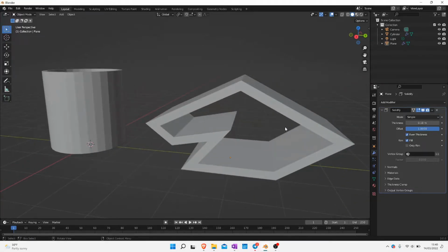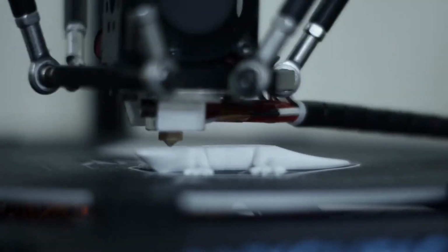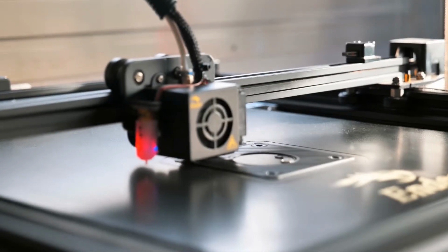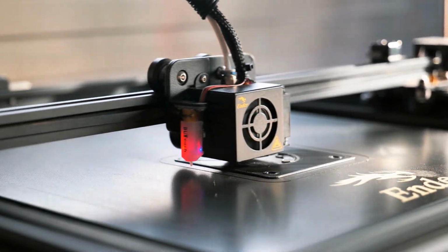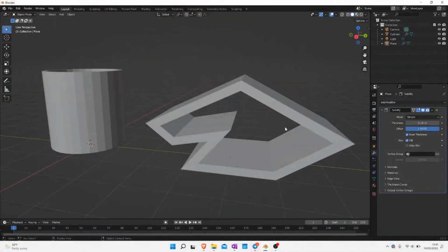Now this is really good if you have a lot of different surfaces, or you've got a very big model. The only thing, especially for 3D printing, you want to keep an even thickness so that you don't have certain walls that are thinner than the others. But it might mean, if your model is very complicated, that the vertices actually pass into and inside one another, which means then you have to do an awful lot of cleanup. But there's a trade-off. You end up having consistent thickness around the model, but there's an element of cleanup required later on.